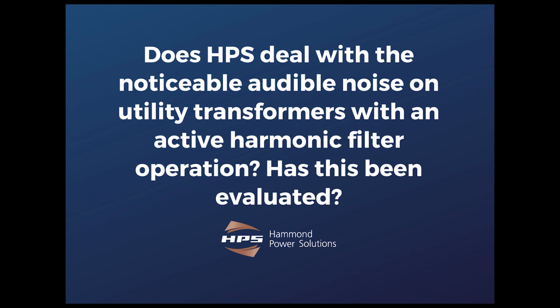I would comment too that the audible noise on transformers can come from a number of sources. While people sometimes assume that the audible noise on a transformer is caused by higher frequency harmonics, the major components of it are often other things. Most transformers, the major reason for the hum is simply the core vibrating.